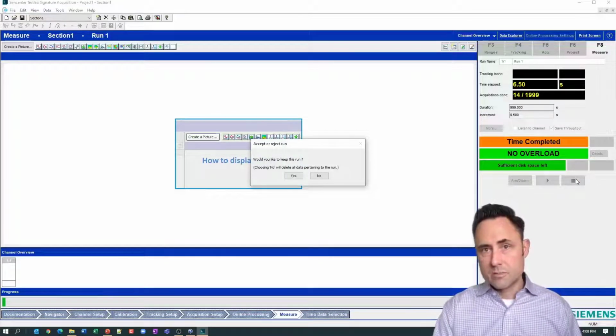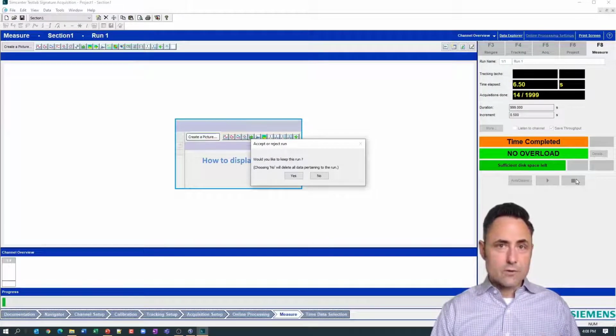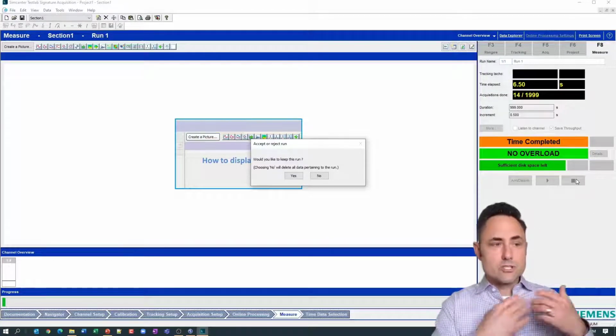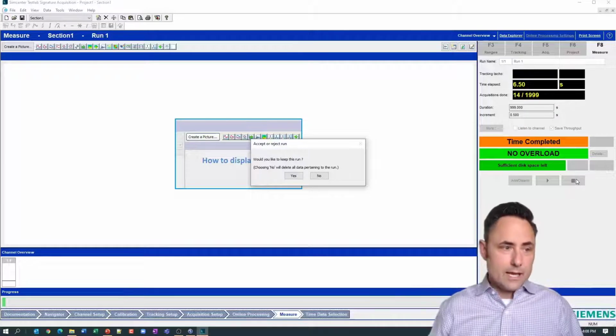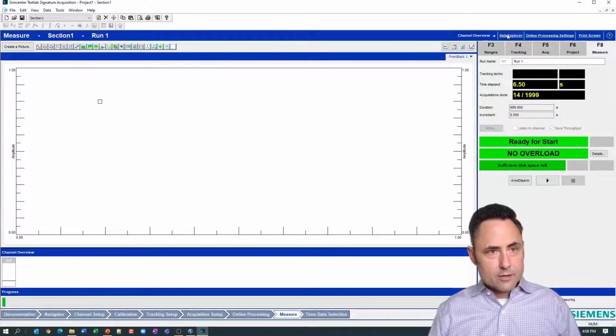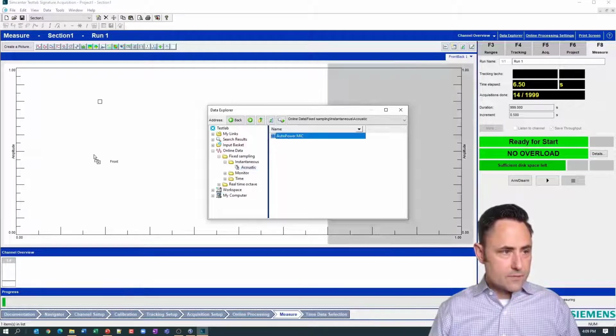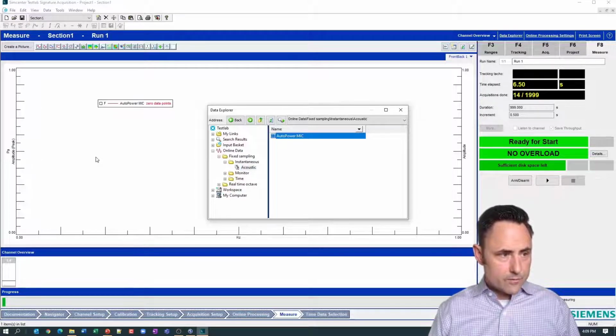Okay, so this is no frills. You see there are no displays active or anything. This is just base how the software opens when you open it. You can certainly add a display and add some data there. I'll show you how to do that. And so I'll create a display here. I'll create a front back. I'll go over to this Data Explorer, and I'll grab some instantaneous acoustic data, and this will be the auto power of my microphone.